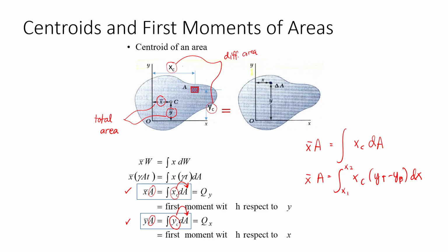Now again, since we're going to solve both, since we are using the vertical strip in terms of the bar y aspect, since you are already using the vertical strip for the x component, you have to be consistent that in solving for the y aspect, you're going to use the vertical strip as well. So it cannot cross over. If you're going to use vertical, you're going to use vertical strip all throughout the problem in solving for bar x and bar y.